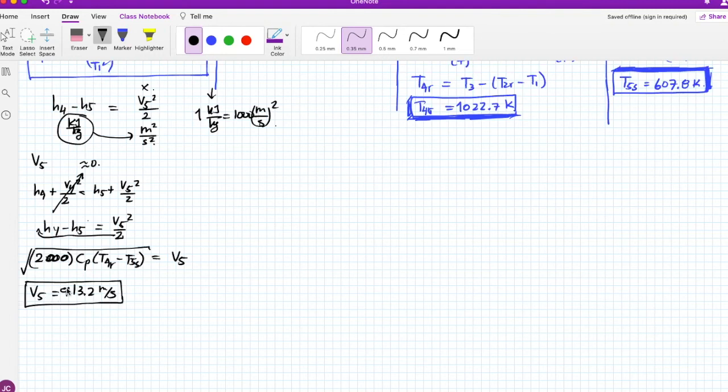So we started with zero, and by using the thermal energy, we converted this into 913.2 meters per second. Oh, so this is supersonic, right? Yeah, this is supersonic, like Mach 3, maybe. But the plane is supersonic? No, the plane is not supersonic, but the air leaving the plane is supersonic.